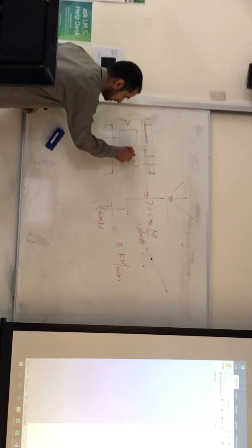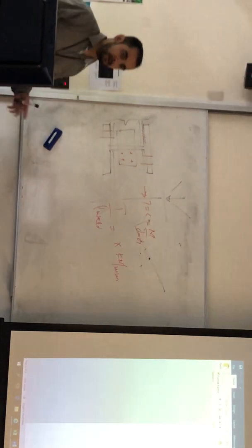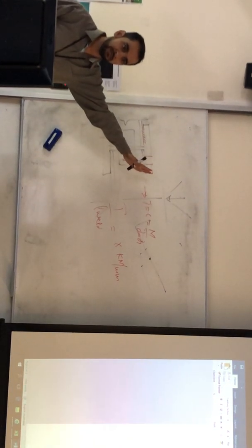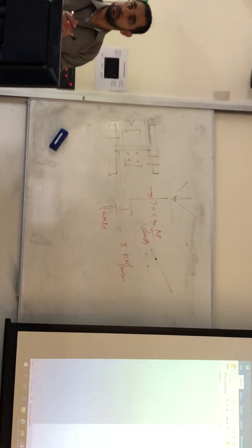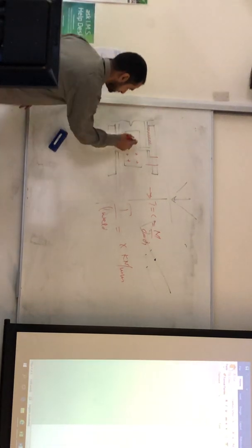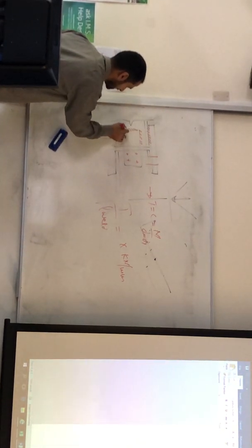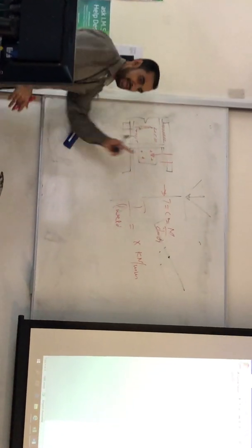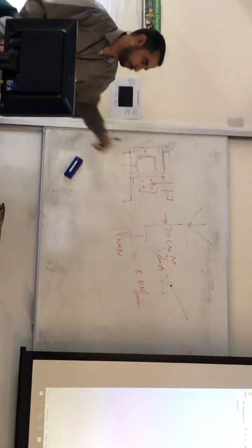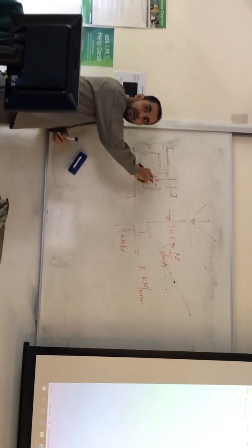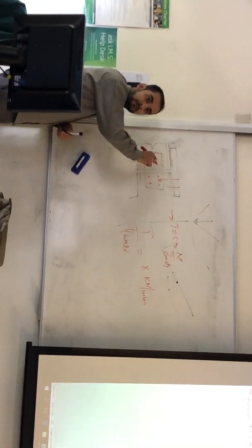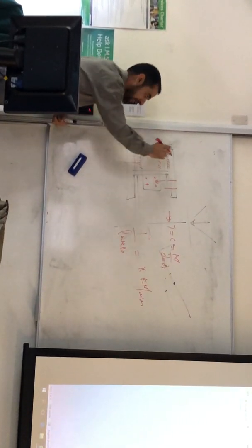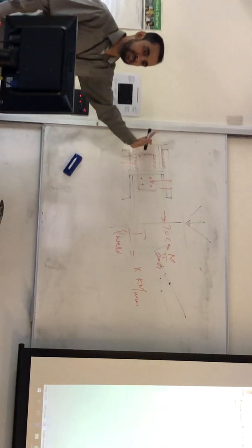Now coming to the web. Some of you use the moment in the beam, which is not the case. Some of you use axial load, there were lots of things. Simple is, let's say one side is weld or both sides is weld, right? There is a shear force in that beam, in that web. That shear force has to go to the bolts and to the web splice plate, right? And again back to the weld and to the web on the other side.